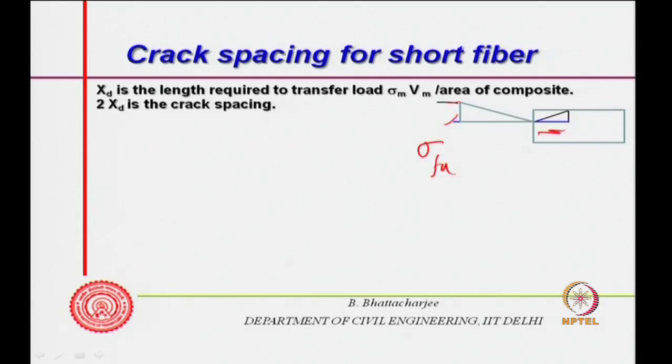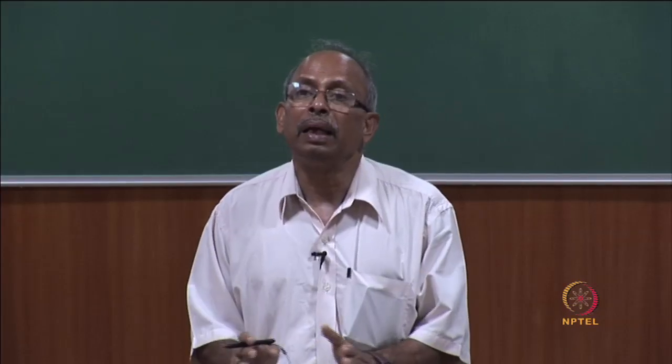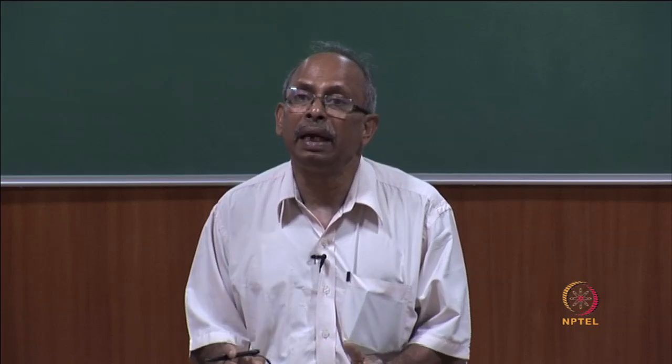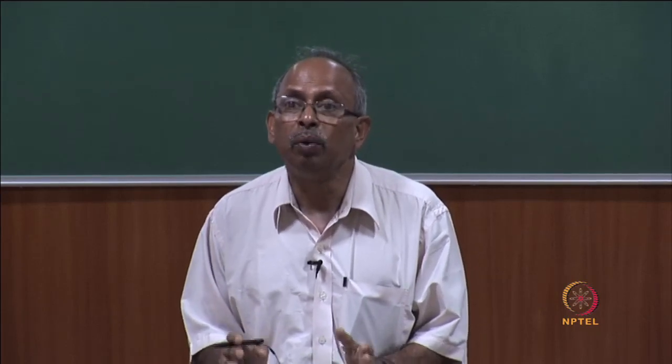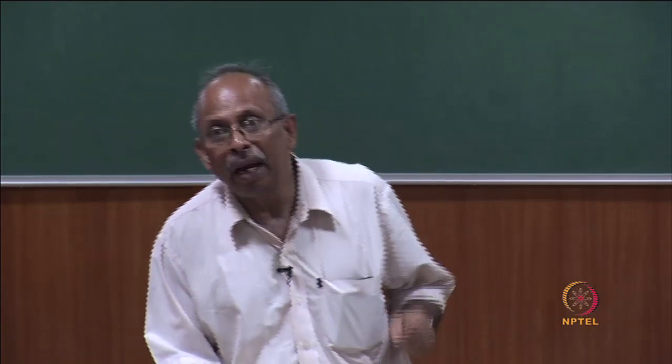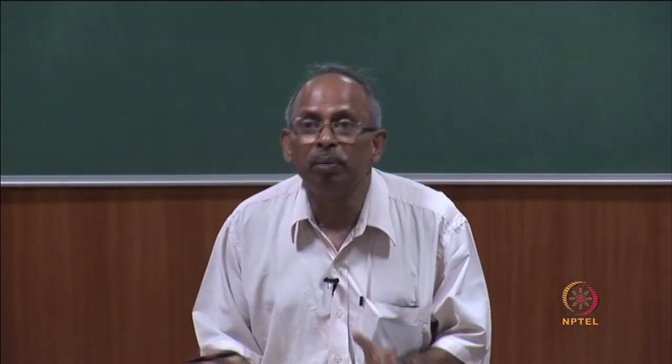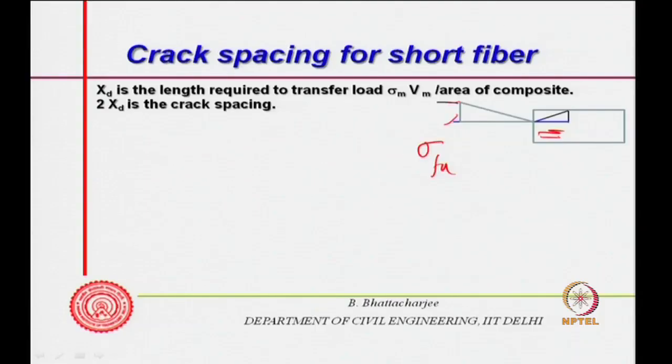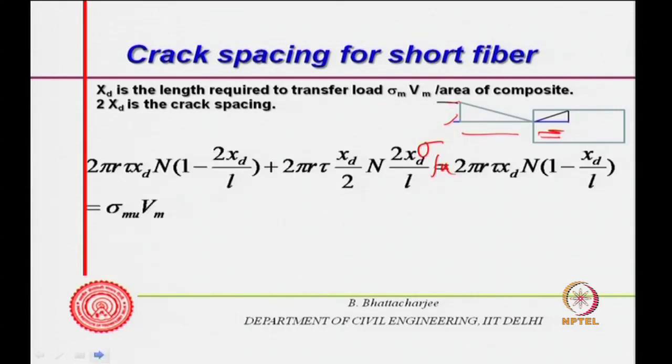So, one side you will have length, because even if you have sufficient length, let us say L c, critical length, it is very unlikely that both sides it will be 50-50. Only one side it will have part development strength, development length will not be full. On this side you may have development length plus more. So, therefore, the effective number of fibers one can modify.